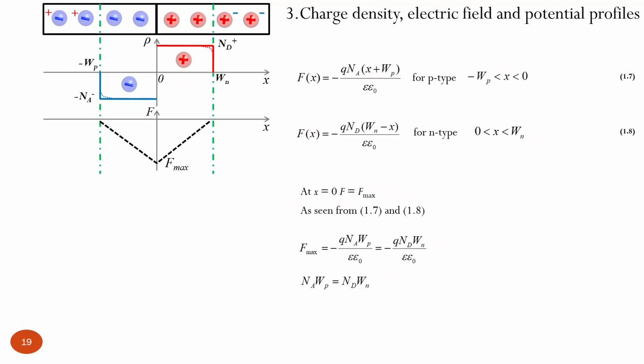So these space charges obviously create an internal electric field, and this electric field forms, first of all, a potential, because of electrostatic potential distribution. It forms a potential barrier for diffusion of majority charge carriers and enhances drift of minority charge carriers. These fluxes of charge carriers compensate each other, and eventually we have equilibrium condition. So we went into details and tried to understand what the profile will be.